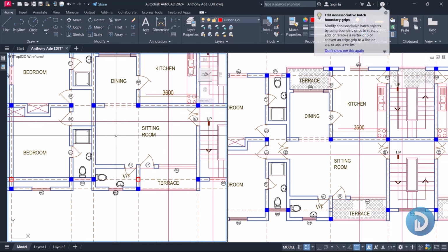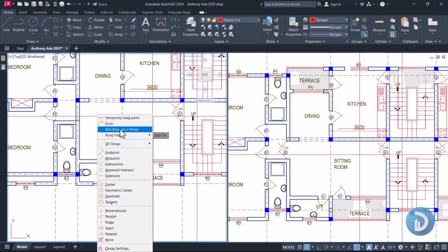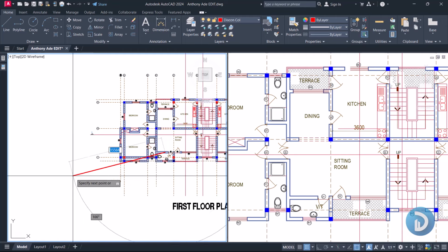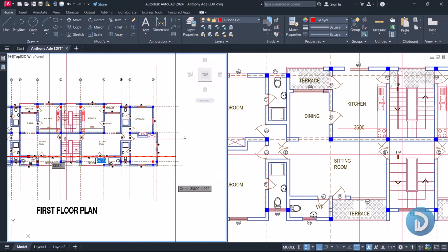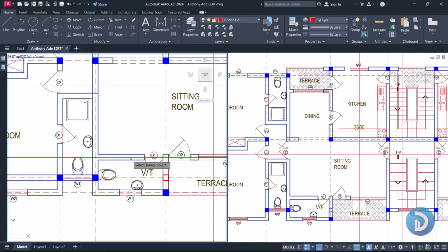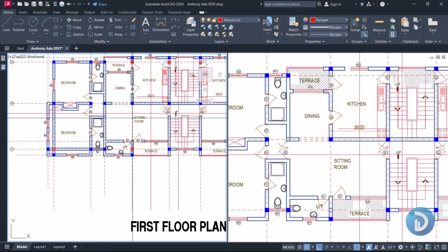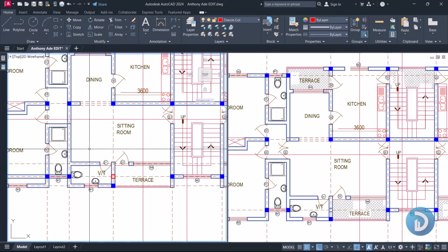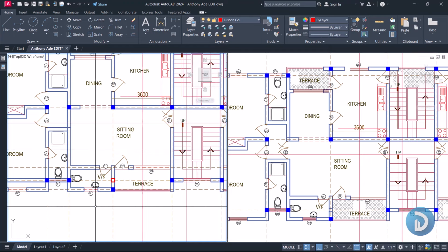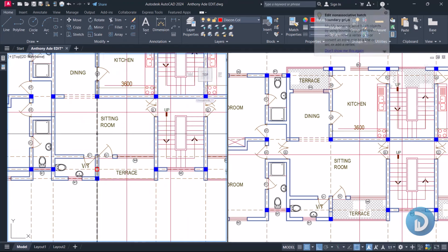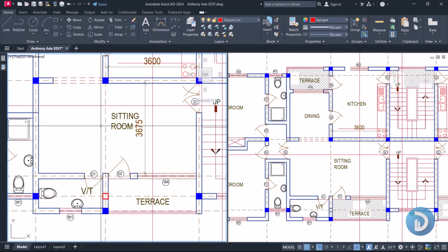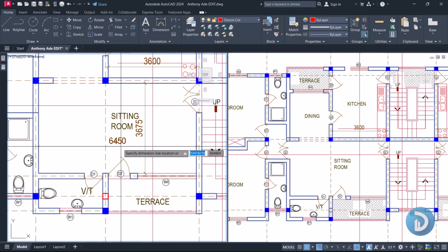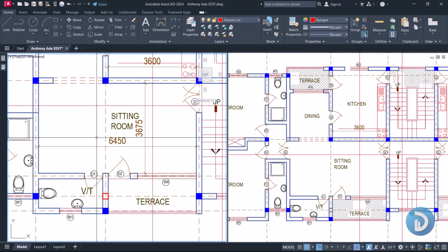Okay, so we create a grid line at the midpoint between these two. Put on the auto. We'll extend this out. We'll match the properties. Okay, so we'll have a panel here, and we can choose to treat this other part as another panel. Why do we choose to treat this other part as another panel? So let's check this dimension. We have here as 3.675, and we have here as 6.450. Okay, so this is the full width of this slab.